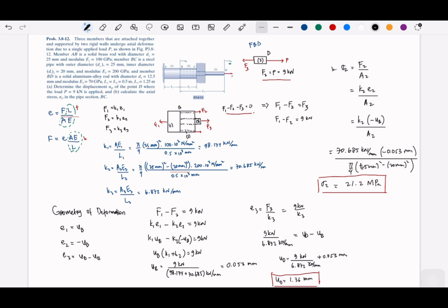So basically the key component of our problems is we need to have the axial deformation formulations, either using K or using F. We can compute all the components in the axial deformations. So we are left with the force and elongations. That's actually how we can differentiate between the basic force method and displacement method.